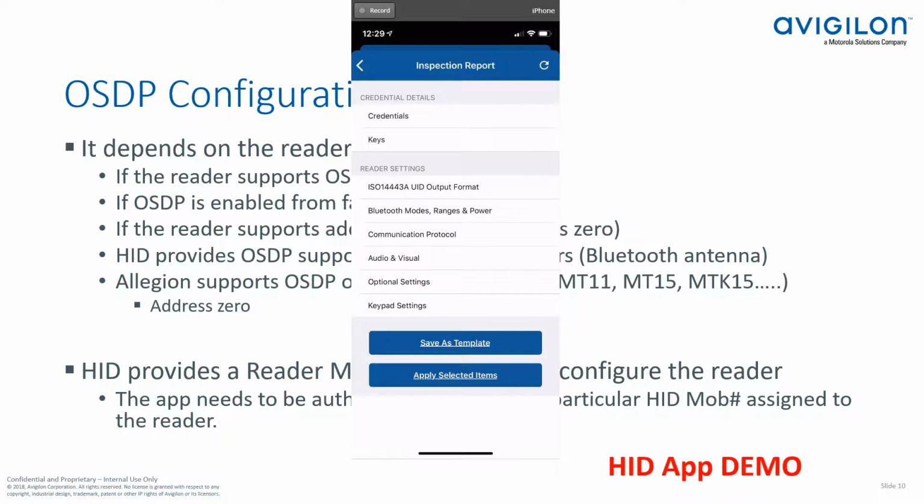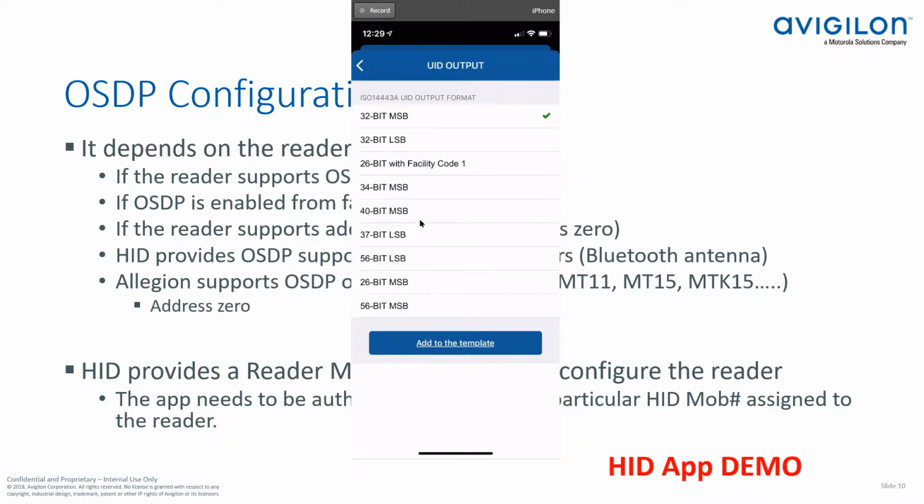If I'm doing that, then I can click on this option right here and select what format output I want to receive for that particular number. I think by default it's just 32. You can configure to one of those different bytes. So this is not the encrypted number of a credential. This is the external user ID. It's a serial number that credentials will have in case you're connecting this to a reader that is not capable of decrypting the secure sector of that credential, of that token, of that badge. So you can go ahead and add that.